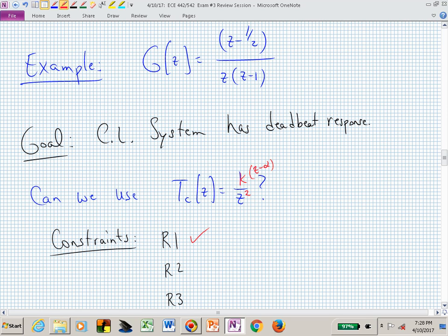The question was, if we had a pole at the origin and then we had 2 poles with imaginary components, and I'm assuming they're inside the unit circle, now they're no longer going to be deadbeat, because now they're going to oscillate, or they're going to collapse, theoretically, in an infinite amount of time, not in a fixed number of steps. The deadbeat response says, if you have 2 poles at the origin, then after 2 sample periods, you've beat your response down to where it's locked on to its final value.